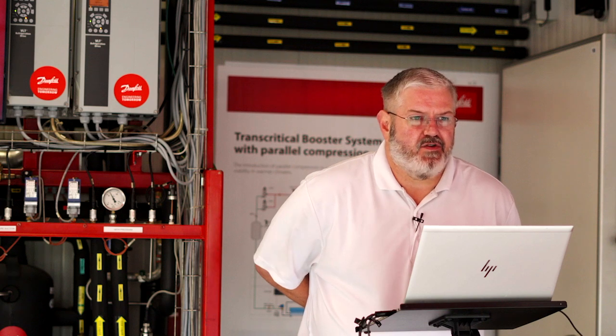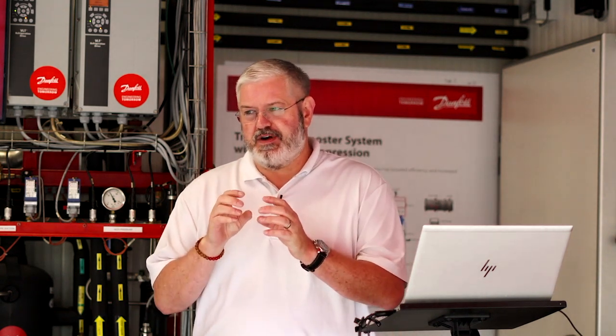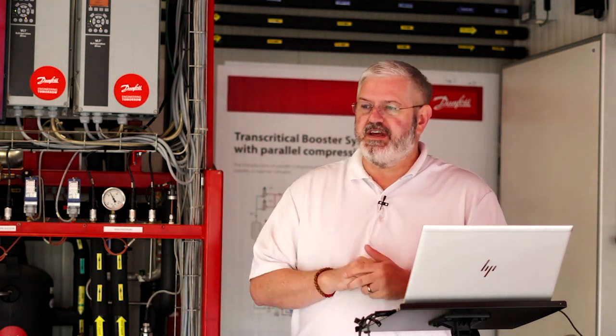Let's see, we have a question. Are the ejector nozzles able to modulate to adapt to load changes, or is it an on-off operation only? It's on-off operation only. I think it's because of the pressures that high with the small size of the components. It'd be really tricky to get a stepper type situation there, or to even pulse it.